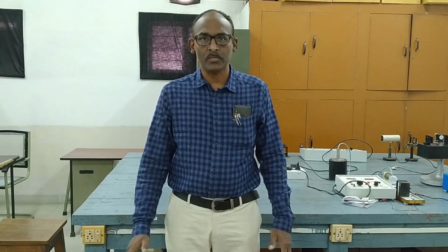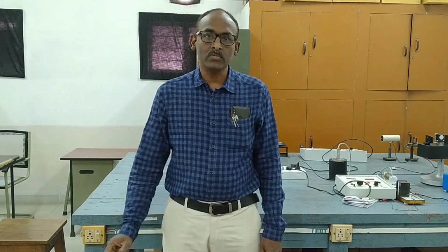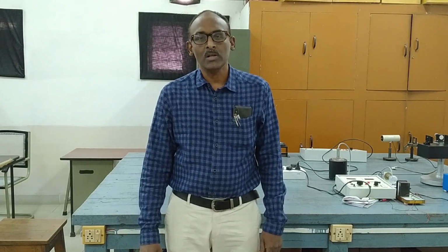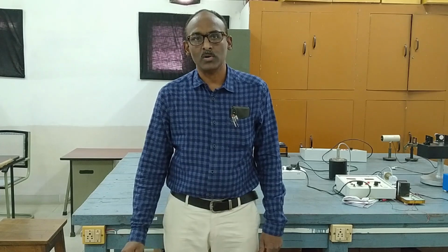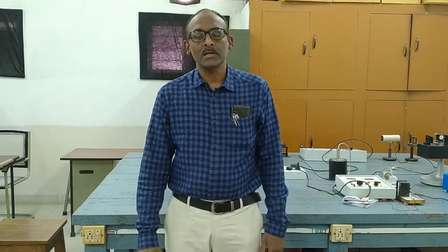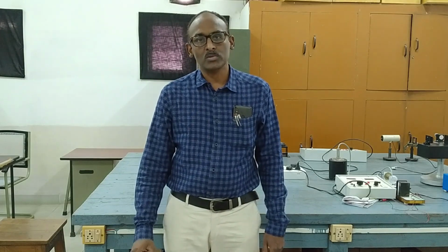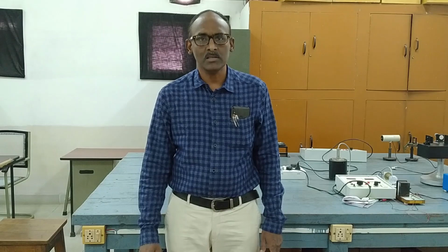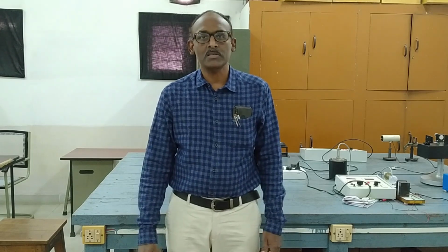These photodiodes can be operated in two different modes: photoconductive mode and photovoltaic mode. The photovoltaic mode is also called zero bias mode, where we don't apply any bias but the incident light makes the current pass through the circuit. For example, the photovoltaic mode operation of a diode is a solar cell. This is also there in our experiment. We will see the solar cell experiment shortly.